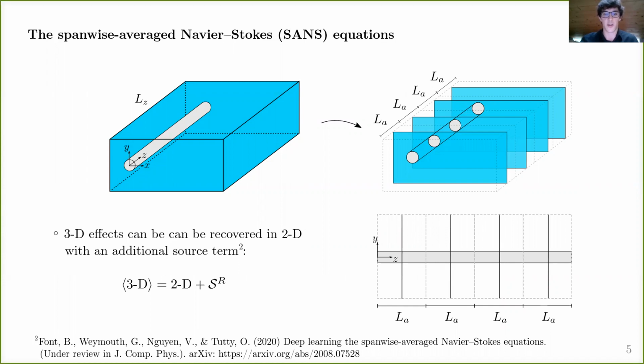So it consists of the spanwise average part and the spanwise fluctuating part. This spanwise fluctuating part is what adds the 3D effects into the 2D solvers that we are looking for, and that would eventually bring us back the spanwise average solution of the flow, as you can see in this simple equation here.